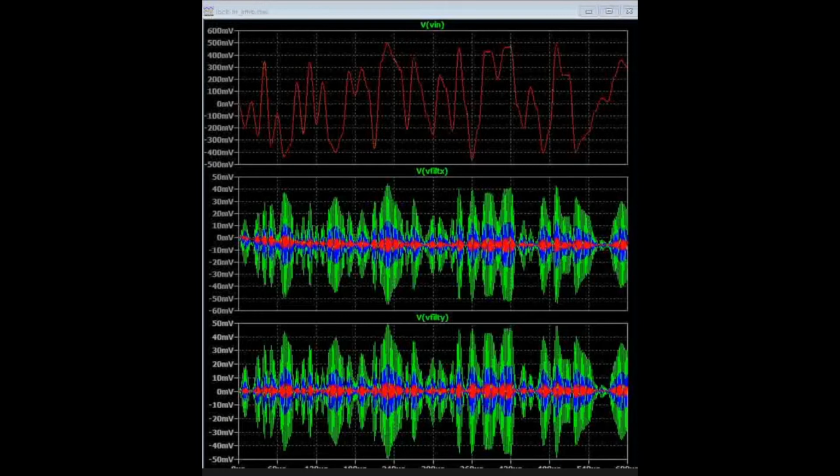30 microseconds or so per transition. So you would expect a signal of around 30 to 40 kilohertz. Okay, that's what you would normally think. But we'll have to guess again, because that's nowhere near what this signal actually is, the repetitive part of the signal. It's actually much faster and much smaller than what you're seeing on this graph.